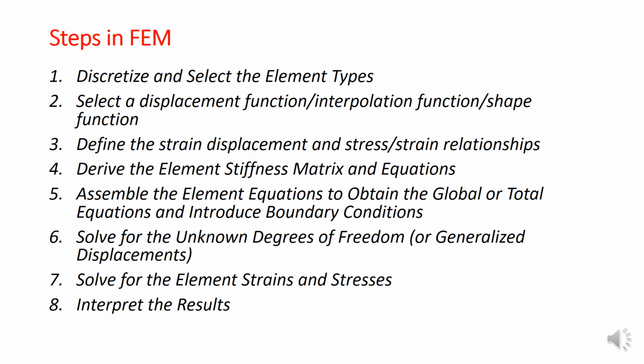So to begin with the steps of FEM, the first is the discretization and the selection of element type. We will see one by one in detail in the coming slides. First, let me go through the steps involved in the solution of FEM. Then select a displacement function, or interpolation function, or the shape function. Then define the strain displacement and stress strain relationships.